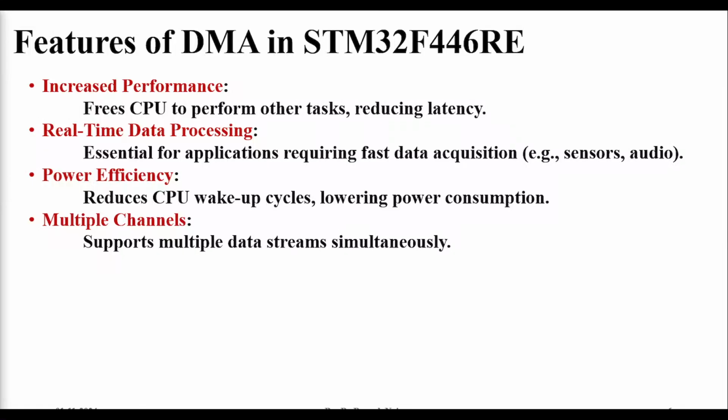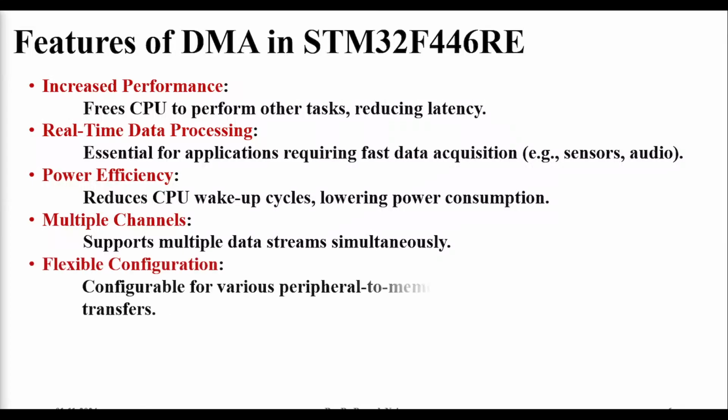DMAs can have multiple channels. So in parallel, they can stream data between multiple devices or multiple peripherals. It has the facility for flexible configuration. Therefore, for various peripheral to memory and memory to memory transfers, we can have different types of configurations for transferring the data.